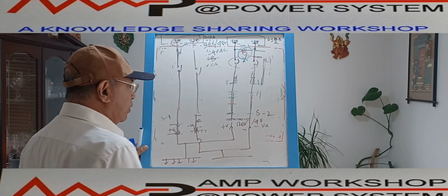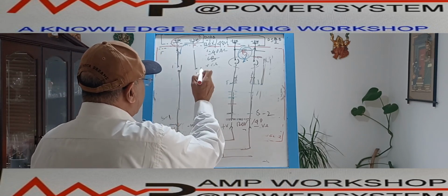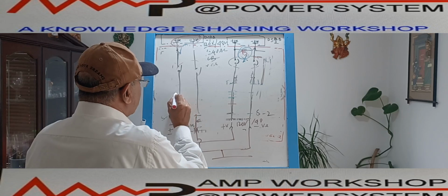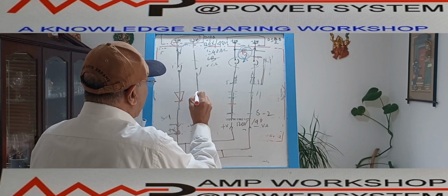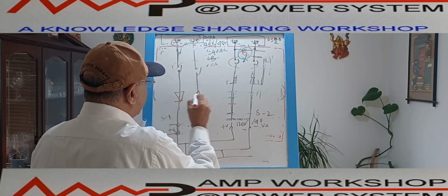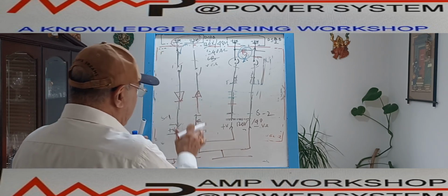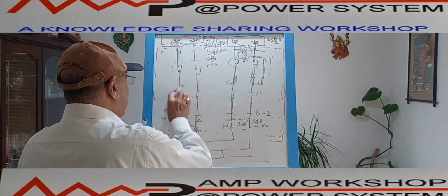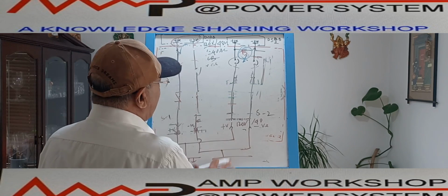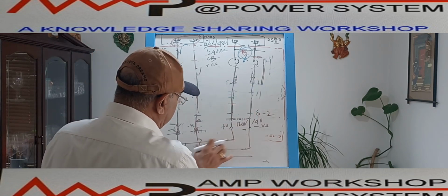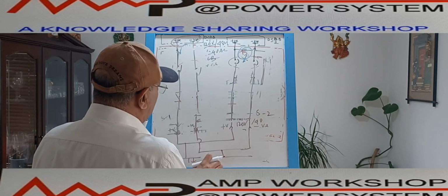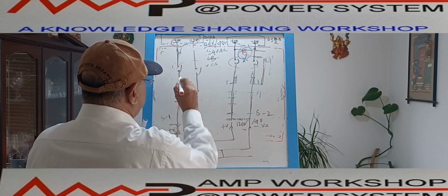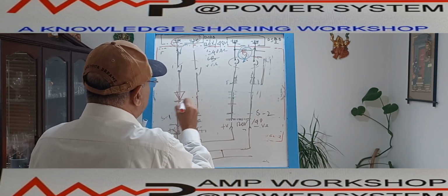Okay. What will we do in that case? In case of failure of one source, the other will be there, but at this time backfeed is also there. So we will put 2 diodes over here in the reverse direction. This is forward, this is reverse bias. In normal condition, if the diode is not there, no problem. Power will go in both cases, and in case of failure of one, the other will supply the power. But in case of failure of one, this power will not only feed the load, it will also go to the backfeed. To stop the backfeed, we put the diode over here.